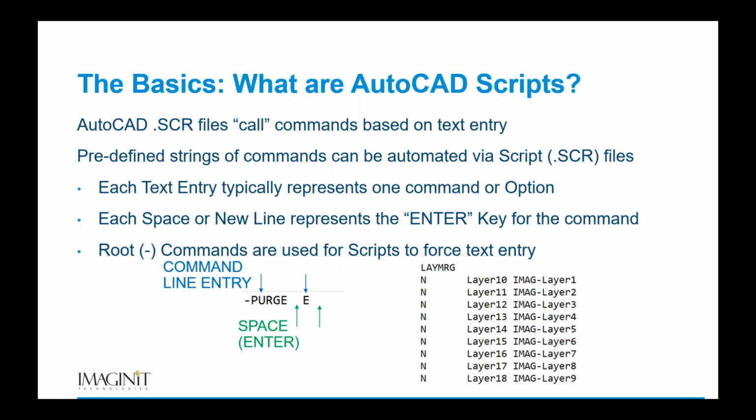They're very, very easy to create because they are just a text file, and they're very, very easy to run because all you need to do is drag and drop the file into your AutoCAD session. So it's really just a quick way to get basic level automation.